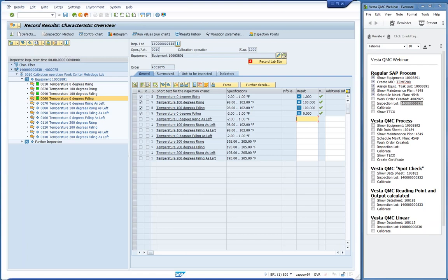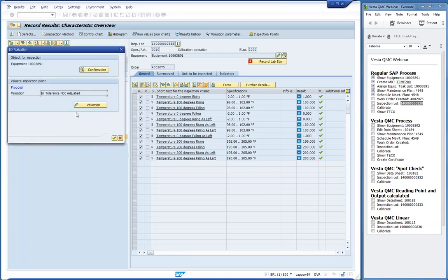So this, as you can see, we'll do all my as found first. So let's say we had 199 and 200 this way. So now I have to go and do the as left as well. And in this case, it'll have to be the same values from before because nothing changed. So this is a bit cumbersome sometimes. And one more. So we will now save these.